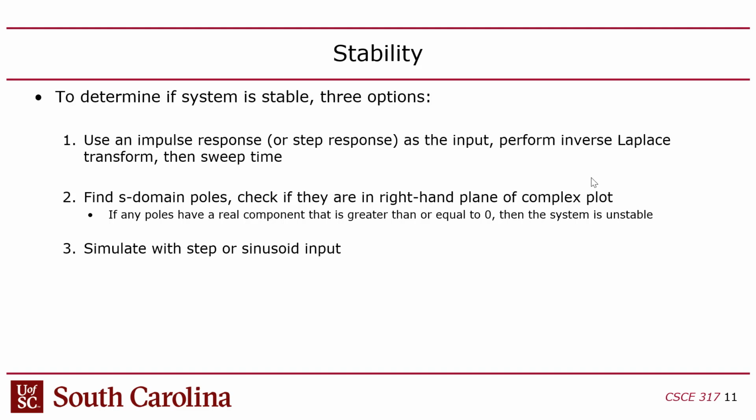An impulse is a function that at time 0, it's infinity or 1. And at every other time, it's 0. So it's basically a pulse. You can think of it like a reset pulse, like when you reset a Verilog module, except it has infinitely short duration, right? It's only non-zero at time 0.